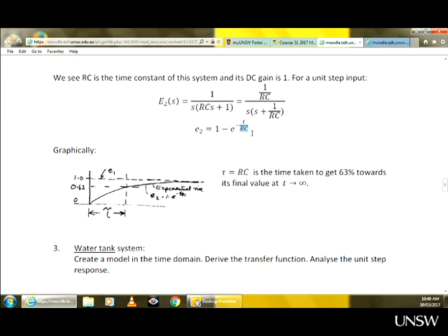But see, if time equals RC, then you have t over RC, which is RC over RC, which is 1. So e to the minus 1 is 2 point whatever. Find the reciprocal value, then 1 minus that will be 0.63. Yeah, I wish I invented this, but it was someone who did it a few hundred years ago. So it is simply a matter of mathematics, substituting the value of the time constant for t, and you will get 0.63. If anyone has a calculator, you can quickly check that.